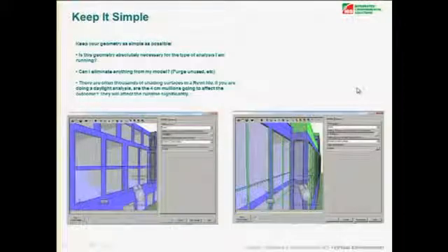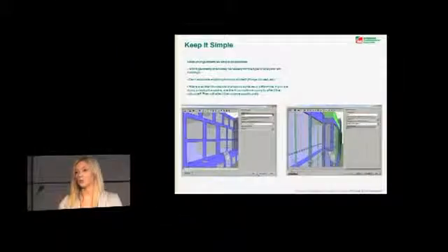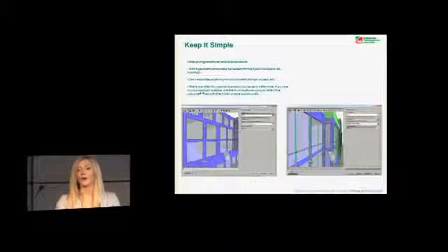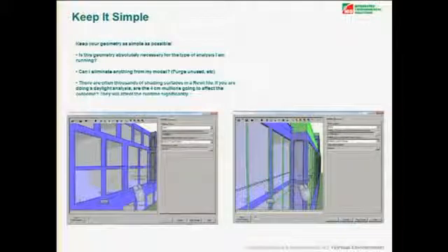But the way that they have to come through is in a mullion family or a roof family. Not a floor family, not a wall, I mean, wall sometimes, depends, but it has to be roof or mullion family. Why? I'm not sure. But if you have done your shading out of masses or that type of thing, nothing else is going to come through. So you have to make sure that if you have done something out of masses, that you're actually going to apply the roof family or the mullion family to that entity to change it into it, and then that will actually come through.